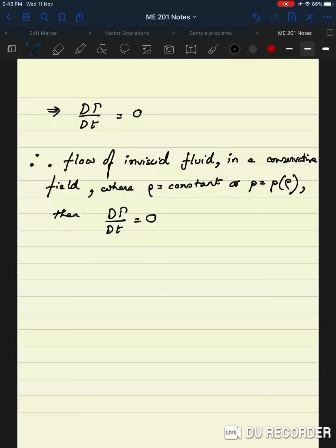So here it is important to note that when pressure is a function of variables other than density, the contour integral need not always be 0. And as you might anticipate, the vorticity of a fluid element may be changed through the action of viscosity, non-conservative forces, or density variations that are not a function solely of pressure variations. So this is our statement of Kelvin's theorem. So let's just box this.